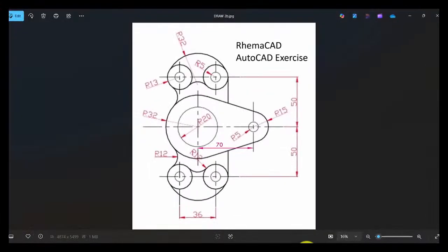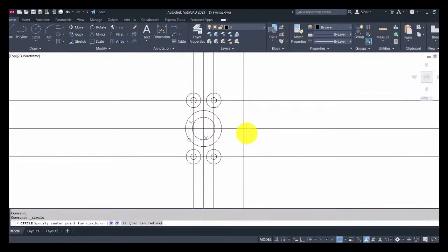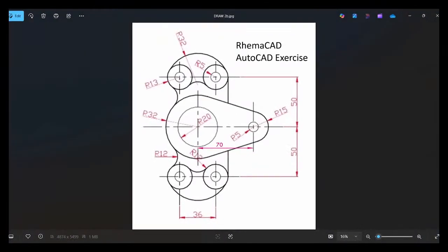All right. Then next, I'm going to come to this hand. I have 2 circles here. I have a smaller circle of radius 5, then another circle that has been modified to form an arc. So we have radius 15 and radius 5. There's a circle here that has been modified; part of it has been trimmed off. So I'm going to draw the complete circle for now. Later I will trim it off. So 2 circles, radius 5 and radius 15. So circle, another circle. All right. So now my drawing is beginning to take shape.